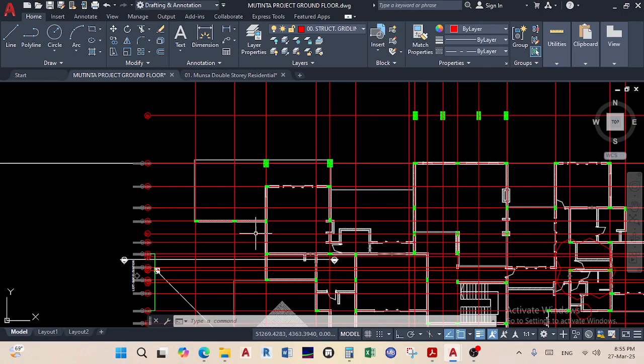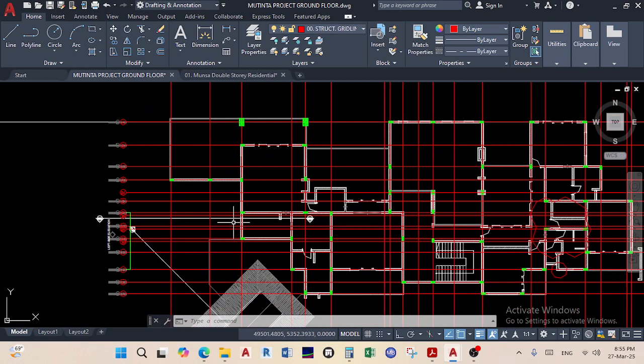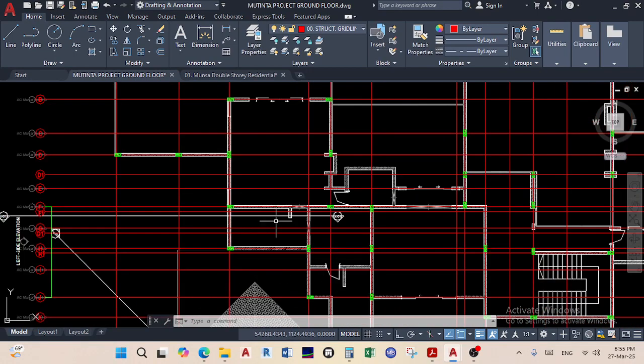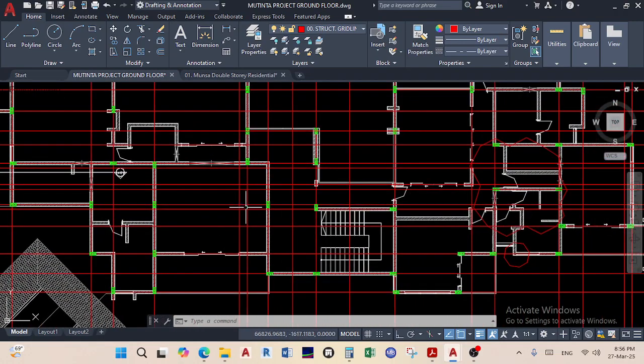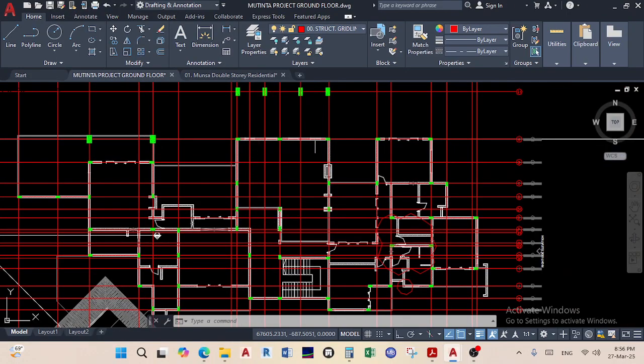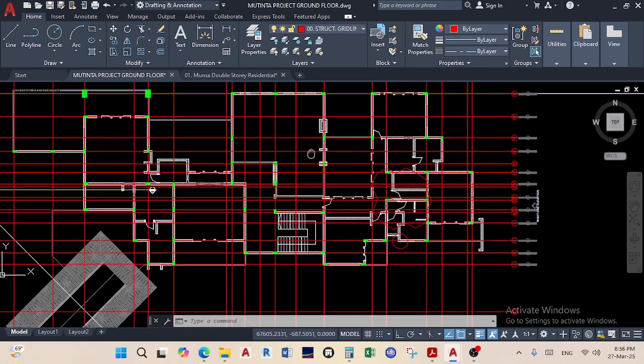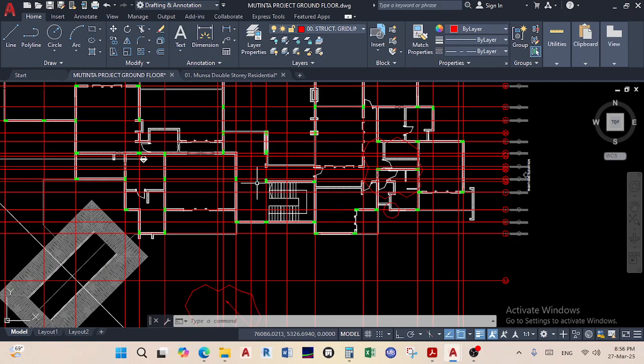Okay. So this is one floor system. It's acceptable. This will be another floor system. If there's going to be a beam spanning from here to here, this will be the primary beam, this will be the secondary beam, and then this will be our floor system. This also is another floor system. It's acceptable. This is good. You can see the way that I'm hovering my cursor. That's going to be the slab. Okay, makes a square. Two-way, that is good.